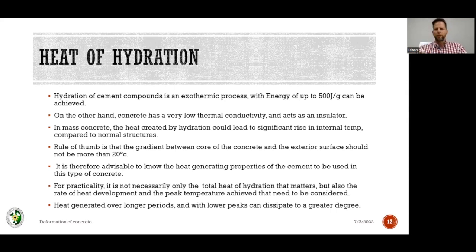After about 5 minutes, it's on site, and the slump is taken, and somebody pokes a thermometer into the little wheelbarrow that was placed there for testing, and says, "Oh no, 31 degrees, 32 degrees, concrete rejected." Take the 6 cubic meters and go stuff it where the sun doesn't shine.